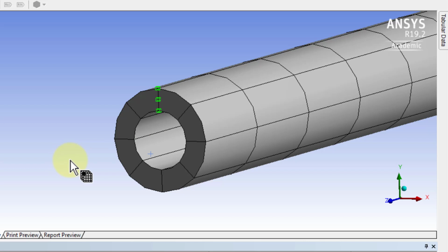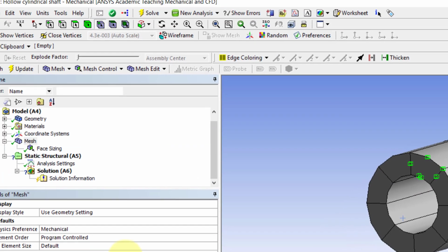And in our case, that might be adequate, but it is recommended that even with the quadratic elements, because we have the mid-side nodes, you'll see that there are mid-side nodes all over. So within each element there's a quadratic rather than linear interpolation, which is good. As we saw, as the polynomial approximation gets better, the errors get lower. So let's increase the number of divisions through the thickness to at least 2.